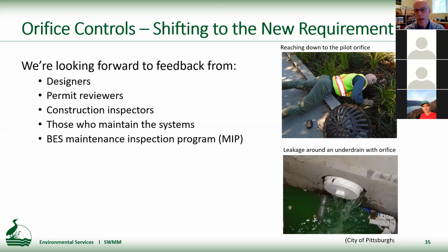And on the lower right, that's a picture from the city of Pittsburgh that was part of a discussion about the fact that simple grout around the pipe, where the underdrain penetrates the beehive or the control structure, and there is an orifice, you can't see it very well, in the nut of that plastic cap. There could be trouble with leakage over time as the grout degrades, and I think we may have standards in the future for seals on those systems.